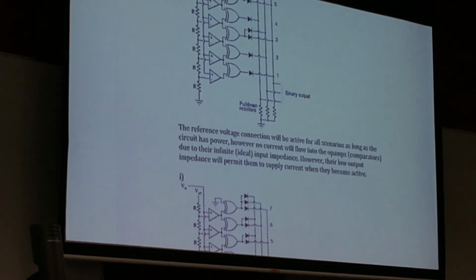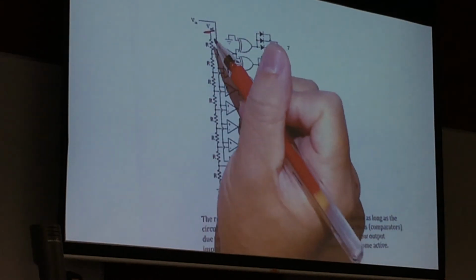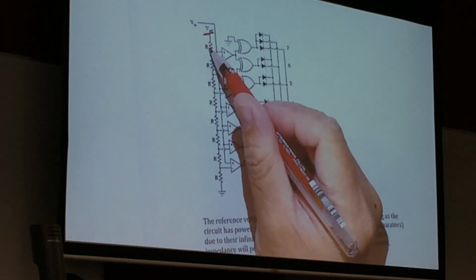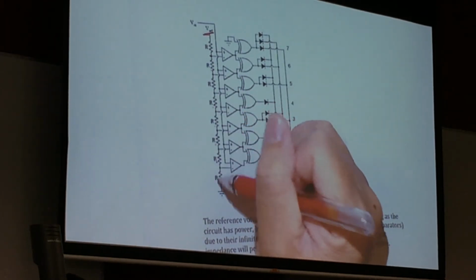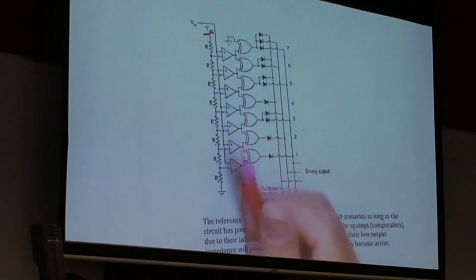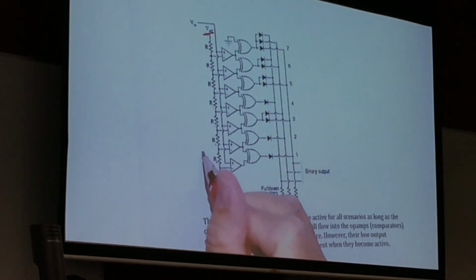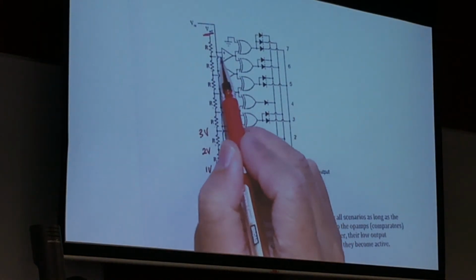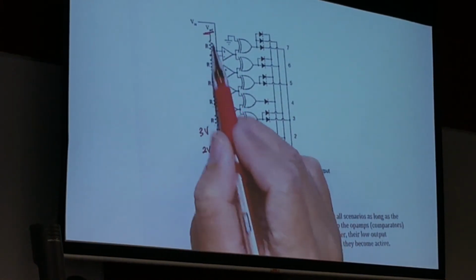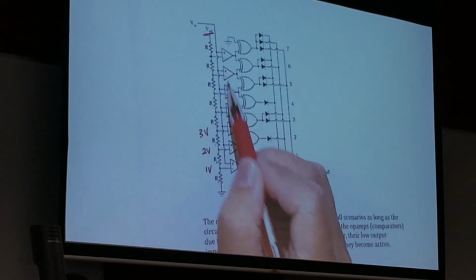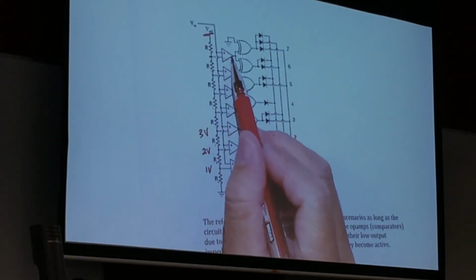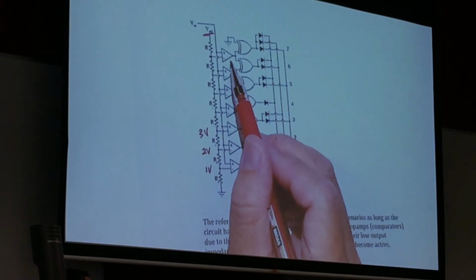Essentially what you need to note is, given the reference, you work out what your voltage is here. Now, there are 1, 2, 3, 4, 5, 6, 7, 8 steps, right? So if this is 8, just nicely, this will be 1 volt, 2 volts, 3 volts, etc. Is that clear? So work out all of this, and note that these reference voltages are connected to your negative terminal. So whenever your input is greater than that particular comparator's reference, the output will be a 1. Is that clear?